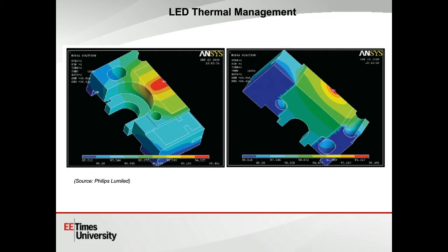So manufacturers and circuit board designers need to minimize the total thermal resistance of every stage to give the lowest thermal resistance from the junction to ambient, in other words, the outside environment.